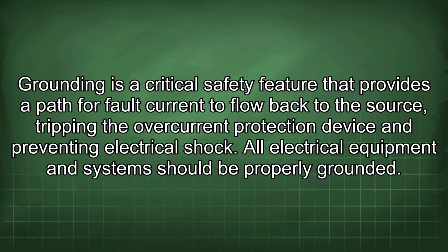Grounding is a critical safety feature that provides a path for fault current to flow back to the source, tripping the overcurrent protection device and preventing electrical shock. All electrical equipment and systems should be properly grounded.